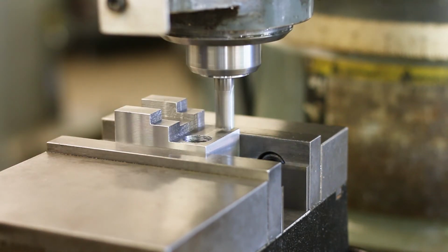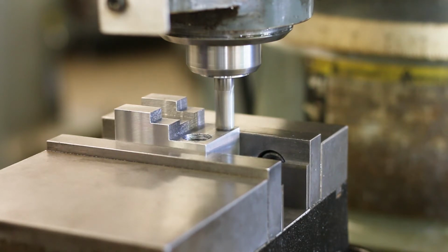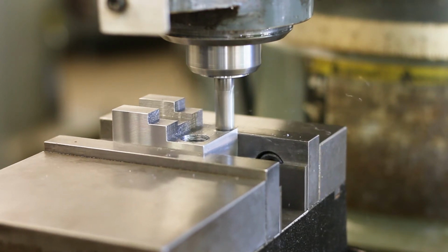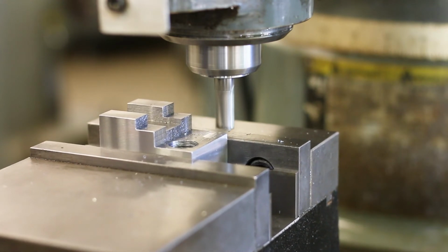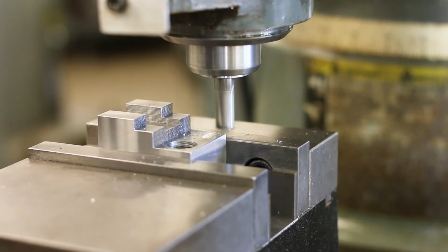Okay, I'm going to bring the knee up a little bit, nice and slow and steady, just until we touch off. There we go. I'm going to call that my 0 on the knee. Then I'm going to back it off, like so. I'm going to go in 5/1000ths of an inch, and then I'm going to take a cut across.